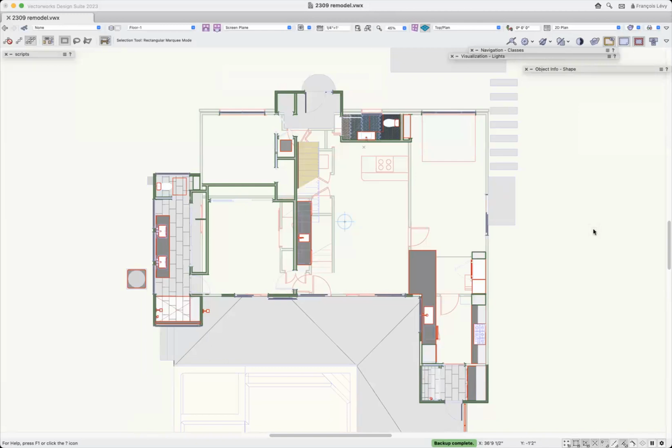Now that's assuming that you create a separate as-built file and that you keep it pristine, which is what we do. And I highly recommend that you do that, because as you're designing, you're cutting walls and putting openings in them and demoing walls, and then you get to the point where you might want to see, okay, now where did I start? You might need to backtrack, maybe copy and paste in place something that you wish you hadn't demoed or mangled. And it might be easier to just go back to that as-built file and resuscitate something there. So for that reason, we keep the pristine as-built file, and it could also help you in your situation.